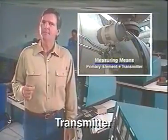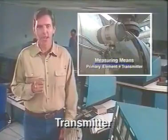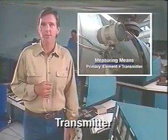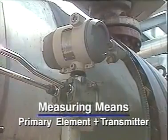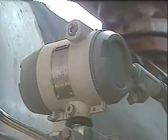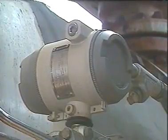Transmitters are another group of instruments. A transmitter gets information from a primary element or sensor and then transmits a measurement signal. Either electricity or compressed air is generally used to transmit these signals. So when we talk about a measuring means, we're usually talking about a primary element or sensor coupled with a transmitter. This is an example of a field-mounted transmitter that transmits flow rate measurements.